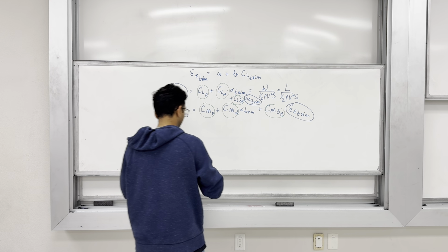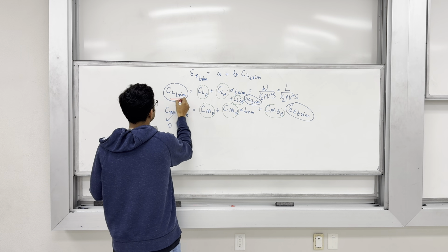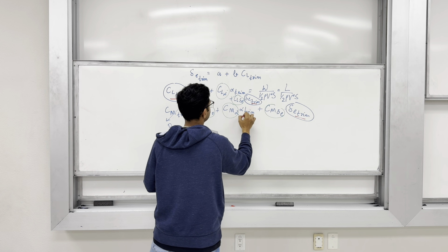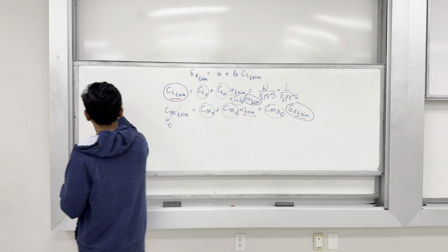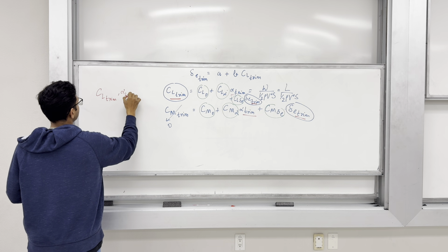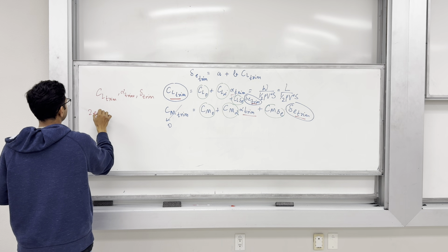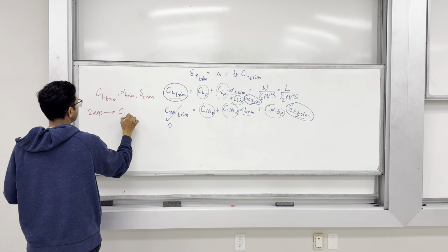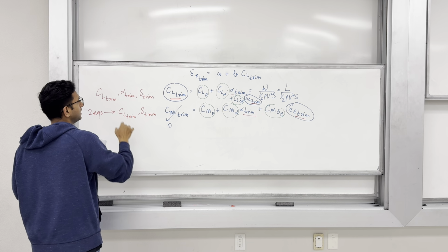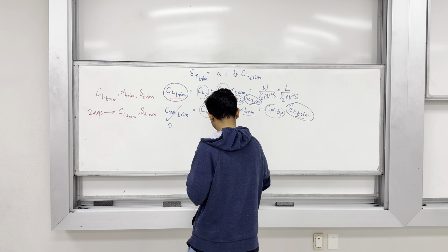So, the only set of unknowns that remain here are CL trim and delta E trim as well as alpha trim, which means that I have 3 unknowns, CL trim, alpha trim and delta E trim, and I have 2 equations which I have to finally condense in the form of CL trim and delta E trim, which means that I have to eliminate alpha trim. So, to eliminate alpha trim, it is straightforward.